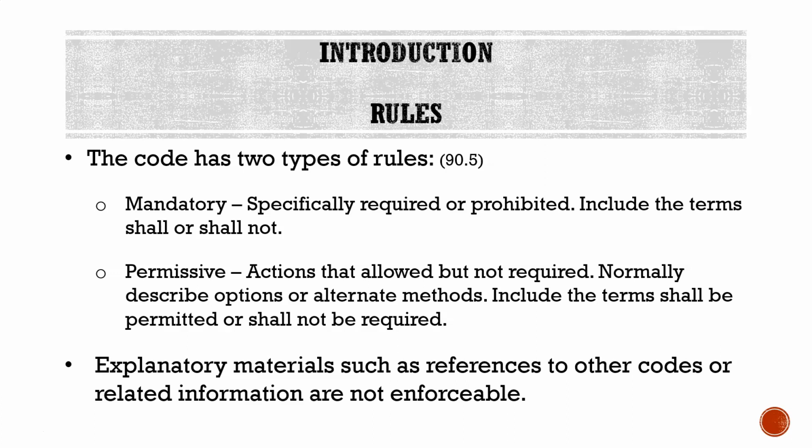not enforceable. As I had mentioned earlier, NFPA writes a variety of other codes. They write, for instance, the industrial codes, fire alarm codes, communication codes, life safety codes, and occasionally in NFPA 70, the National Electrical Code, they will make references to rules in those codes for information's sake. Where it does that, those are not enforceable or applicable to that electrical installation. They're only there for knowledge. So that kind of wraps up what we're going to be talking about with Article 90.